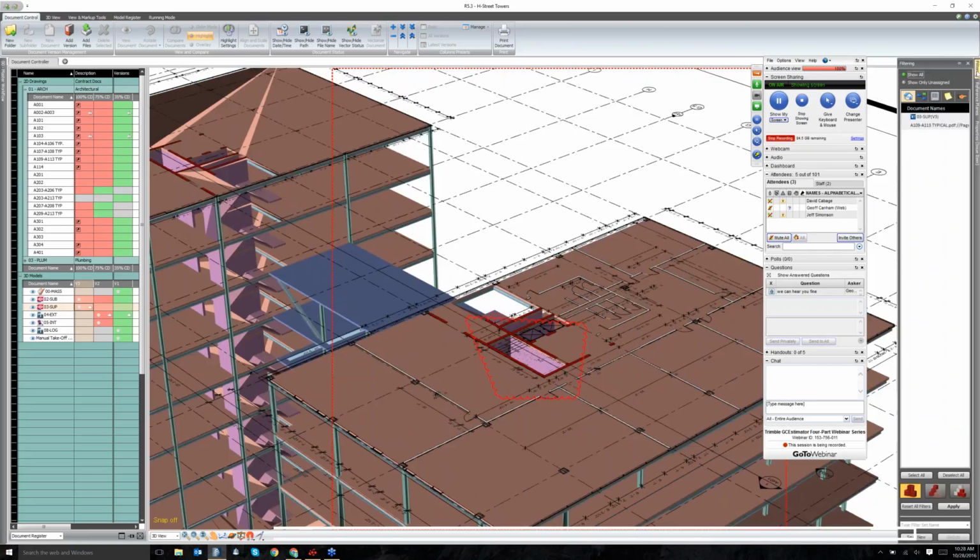So let's jump into a little bit more of model analysis. We've looked at 2D drawings, viewing them, comparing them. We've looked at 3D models, viewing them, comparing them to each other. We viewed 3D and 2D in the same place and created an issue. But another thing that we can do within Vico Office is isolate certain areas of the project. Vico Office works with locations, so we can slice and dice the project with non-destructive areas, meaning that I can break up the project by level.